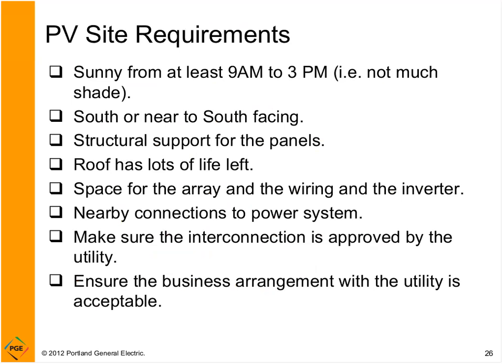Site requirements are very similar to the site requirements for solar thermal. You want to get a lot of sun in the middle of the day, facing generally south. You need to be concerned about structural support for the panels if you're putting them on a roof. Even if you're mounting them on the ground, how you mount them is pretty important. There are a lot of commercial systems out there for ground mounting. You shouldn't discount ground mounting if you have some area that's got a good site.